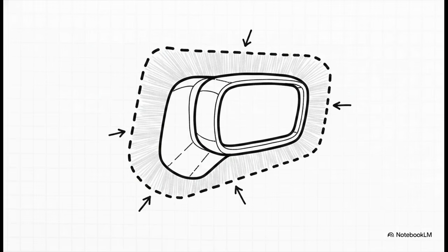So instead of dealing with those messy coordinate dimensions, picture this. Imagine a kind of tolerance tube that wraps perfectly around the part's mathematically ideal shape. The standard calls this the true profile. And guys, that is the raw power of the profile tolerance. Just think about it. What else controls form, size, orientation, and location all at once with just one symbol? Nothing. This one geometric characteristic consolidates a total nightmare of requirements into one clean, elegant boundary that the physical part absolutely has to fit inside.